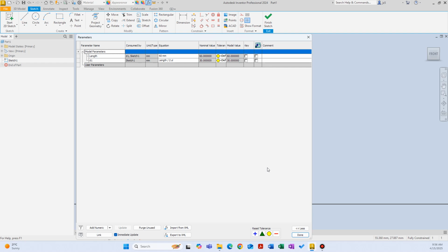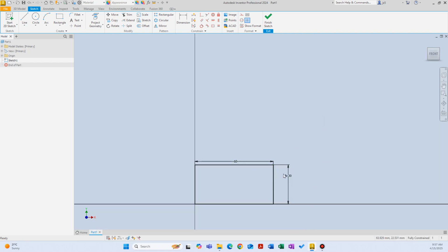By doing that, for example, when I went in and changed the edit parameter name, it assigned it here. But I can do the same thing here as well. In the parameter name, this D1 was my height. I can say height. Now I changed it. Now the height is half of the length. So now let's click OK, and let's go back to height. Now notice that it updated the name of the dimension as height, which is length divided by 2.